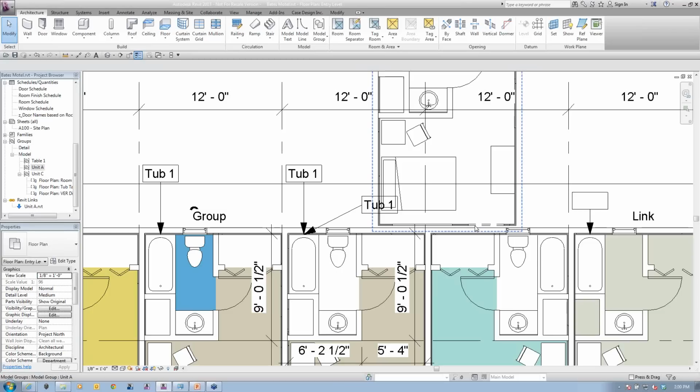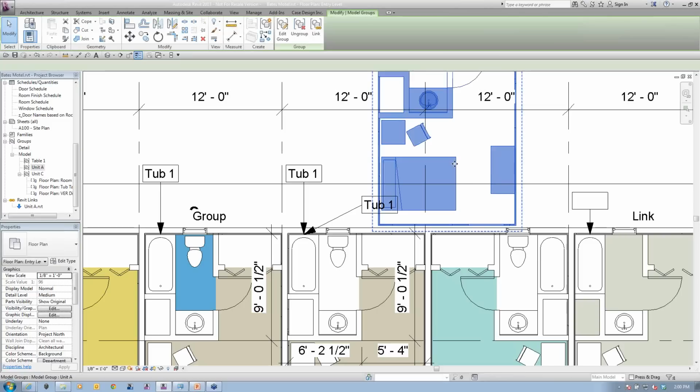So I use this process of creating a wall out of the gypboard layer, where we can handle the finishes differently for the room, but then set it up so that the openings align to the openings with the rest of the project. This is a very nice workflow that a lot of people are getting into, and displaying it this way in here. So I'm going to come in, delete this guy real quick and get back in here.